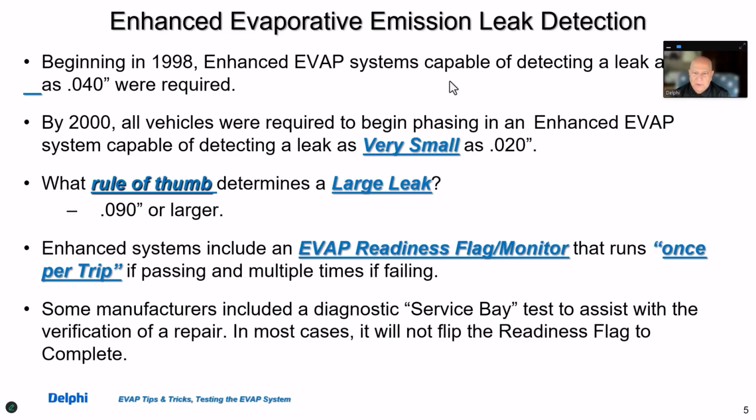Okay, and then also remember, we discussed this in the last class a little bit, you do have service bay diagnostics on some of your scan tools for your aftermarket. For the OE, if they have it, they'll get it. In the aftermarket, you have to be careful because it doesn't mean they always work. They might offer it, but it may not follow through. So just keep that in mind, but please put that on your list of things to look for on the OEM side of your scan tool, your Snap-on, your Autel, whatever it might be.